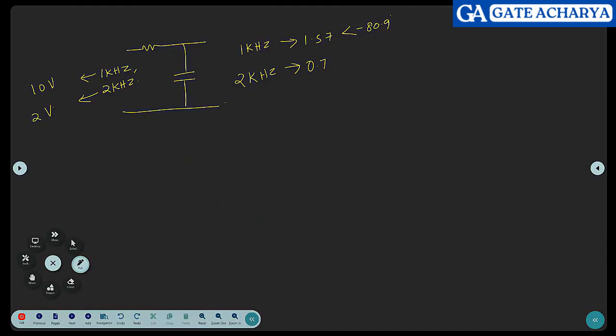So the amplitude here is only 2, sir. You should multiply by 2. How much is it? What did you get? Correct. So you should be getting 1 by 4 pi j plus 1. What is the magnitude for this? Into 2. You should multiply by 2. This is all I care about. For 2 kilohertz, 0.158. And angle is? Minus 85.4.